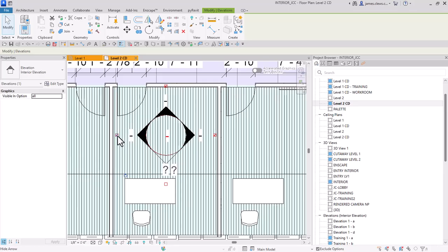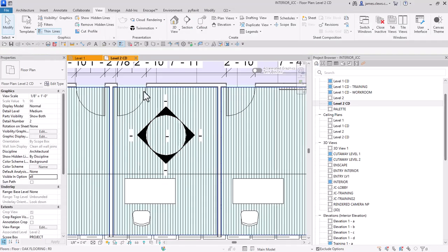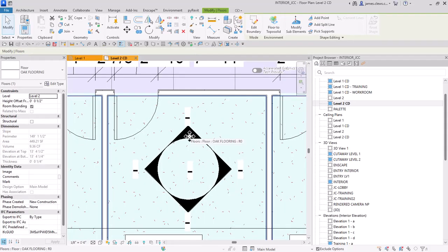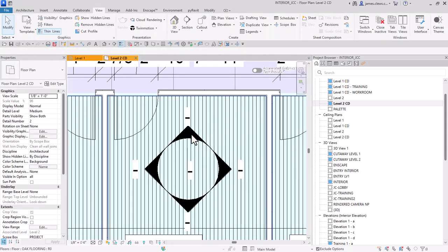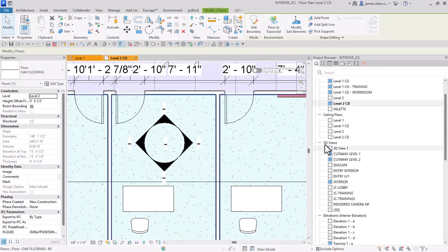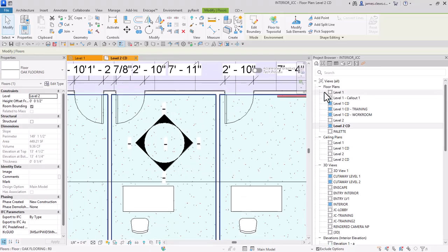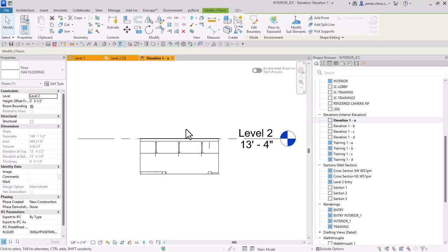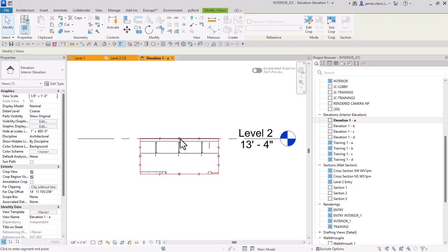So what Revit is doing is creating, if I pick on this, just so you see it, interior elevations that will show me the faces of this model, and it's putting them on the browser under here, right? So I'm seeing interior elevations for this model, but I need to adjust so the width is correct, but the height is something I'm having to adjust here.